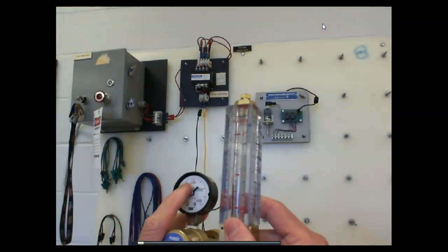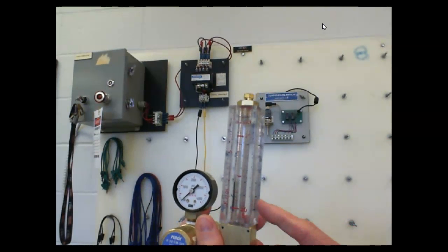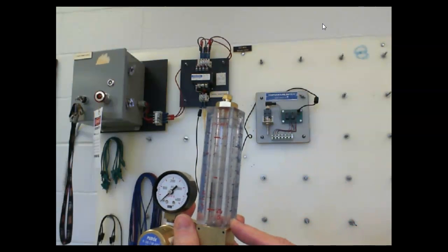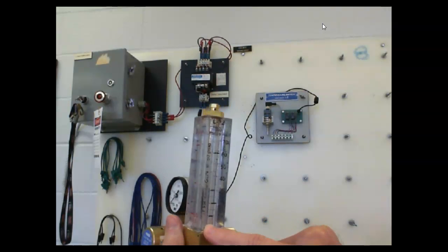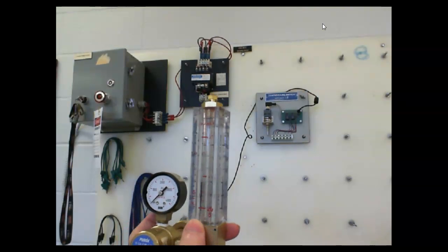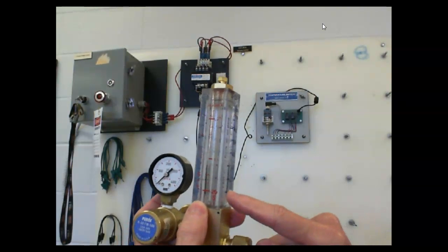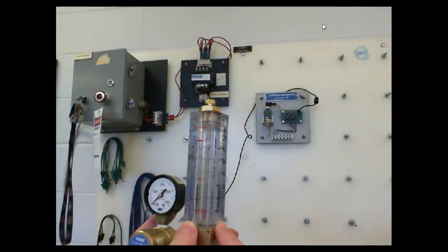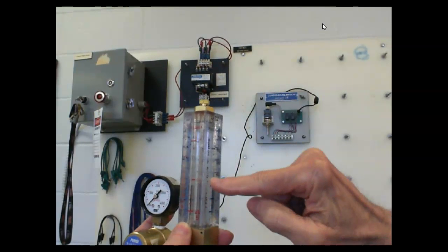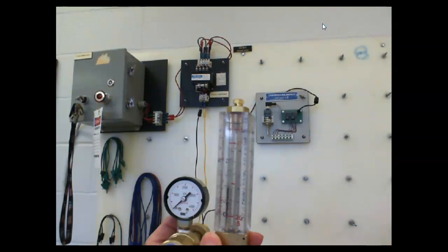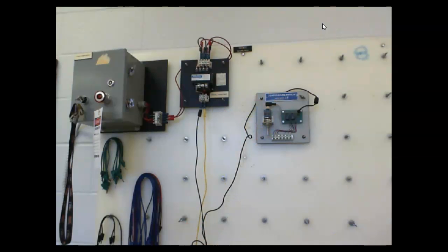So this is the pressure gauge, and then this right here is the flow meter. So it works on the same principle. This has got a metal ball in it, and when the flow comes through the tube, this is labeled in cubic feet per hour. This actually came off a swimming pool, by the way. But the weight of the ball, the rate of the flow, will cause the ball to come up, and of course that would be an indication of your actual flow rate. So this came off a swimming pool, and that's the only flow meter that I have.